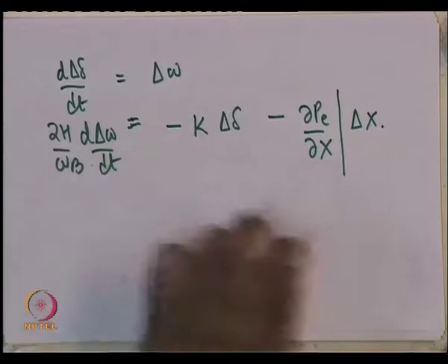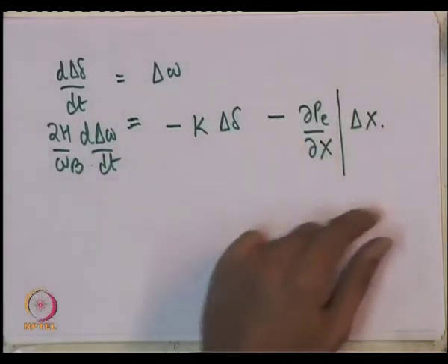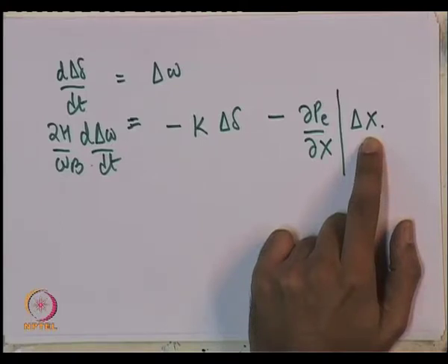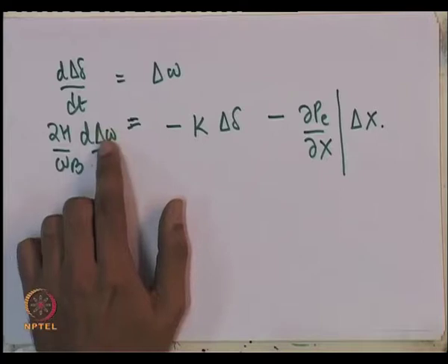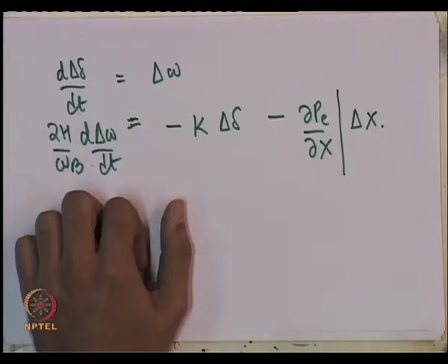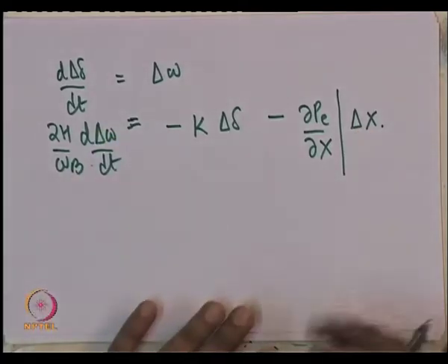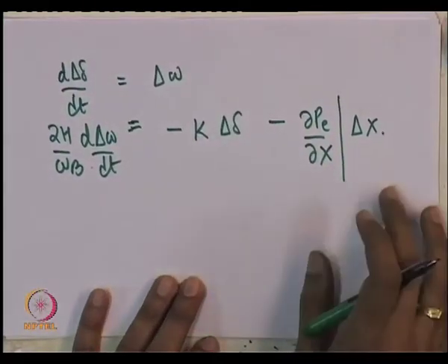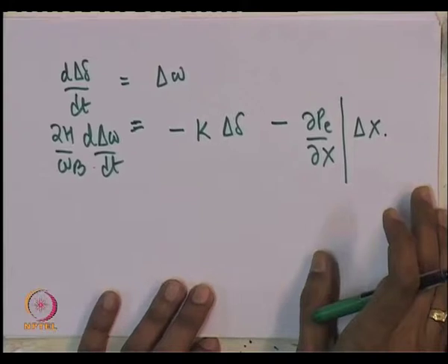Now, a nice idea would be to modulate your x in such a way that you create a torque component which is proportional to the speed. Torque or power component. Remember, torque and power are almost equivalent in per unit if the speeds are not too far away from the rated speed.